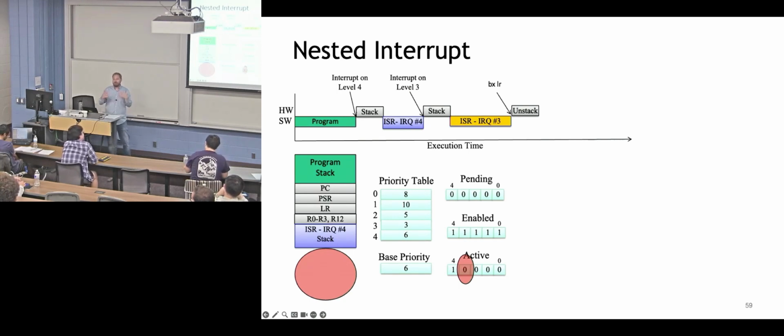In simple cases, you can have a mental model of your processor in which it's unlikely those things are going to happen. But as your program gets much more complicated and you have more interrupts going off, you can have these weird race conditions where something's going off and getting reconfigured. It'll still execute properly. It's not like bits don't get put in registers correctly when you're trying to reconfigure the GPIO. It just might not be what you intended.